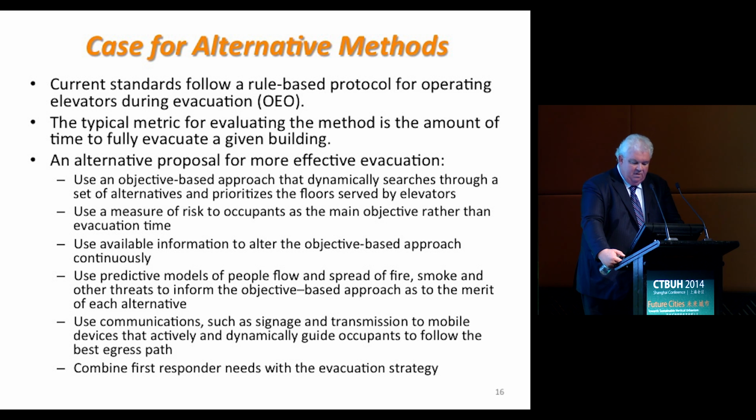You could look at people flow, the spread of the fire, any smoke or other threats to update the approach. And your communications, again, would be critical. Signage, voice signage, and electronic signage, and transmission even to mobile devices so that you could actively guide building occupants to follow the best egress path. And you can also combine first responder needs with this system.